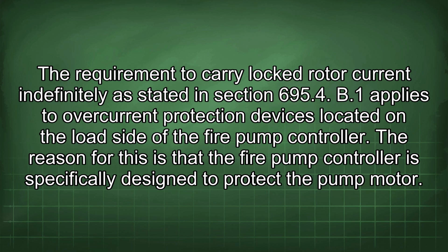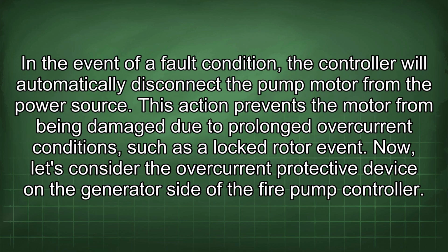The reason for this is that the fire pump controller is specifically designed to protect the pump motor. In the event of a fault condition, the controller will automatically disconnect the pump motor from the power source. This action prevents the motor from being damaged due to prolonged overcurrent conditions such as a locked rotor event.